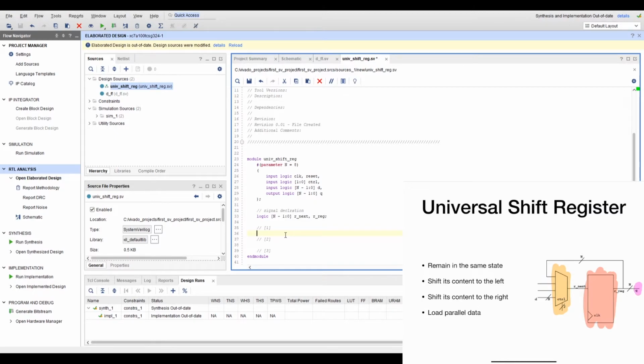For me, part 1 is going to be the register itself, which is probably not necessarily the easiest of the 3. Probably the output is the easiest, but we're going to see that it's actually the register. Well, it's a sequential circuit, so I'm going to use an always_ff. You don't have to use an always; you can instantiate a module, use an always, or use a continuous assignment. It's up to you. I just happen to find that when dealing with synchronous circuits like registers, it's easier to use an always_ff and describe it behaviorally.